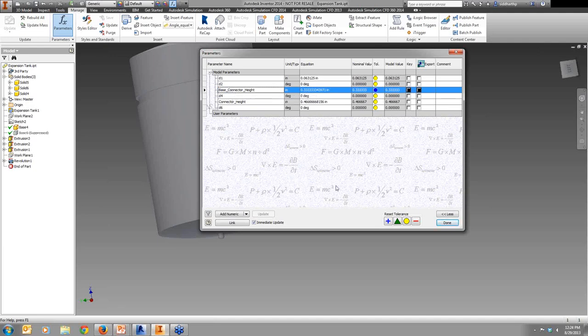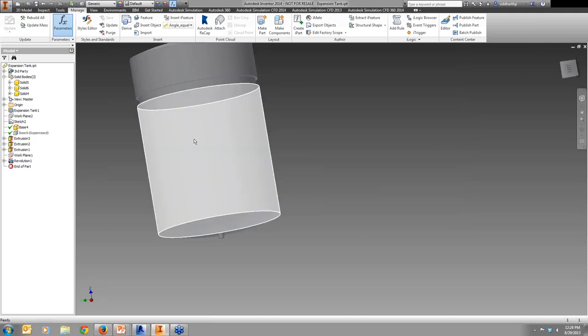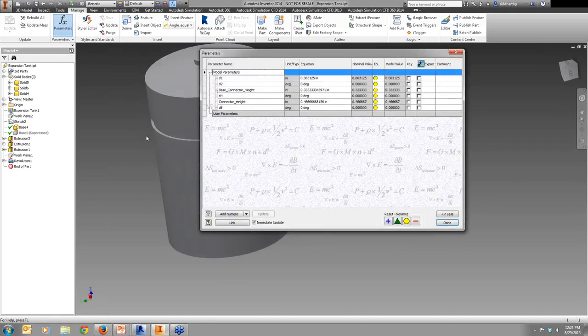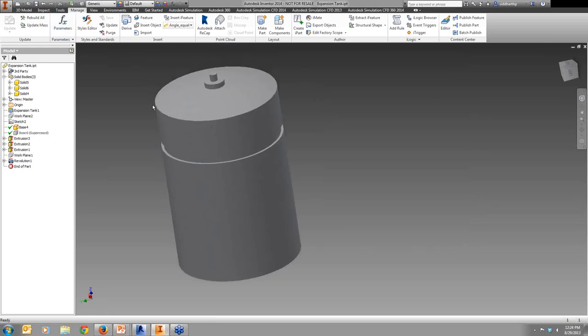Okay, so we can define these variables and I can hit done. The importance of defining these variables is if you do not do this, when you bring it into Revit and you go to the family types dialog box, it will list all of these dimensions with the same name there. So it makes it a little difficult to recognize these dimensions in Revit if you do not rename them at this point. Okay, so that's a slight limitation that you have to work around at this point.